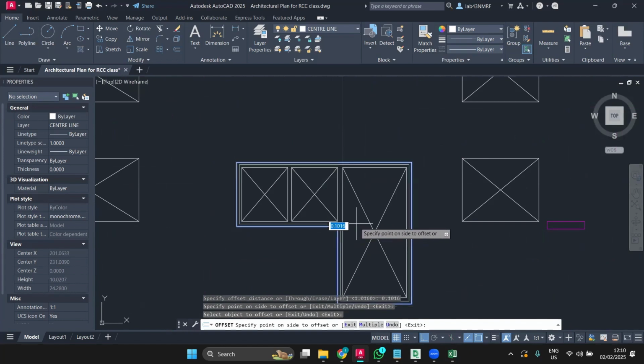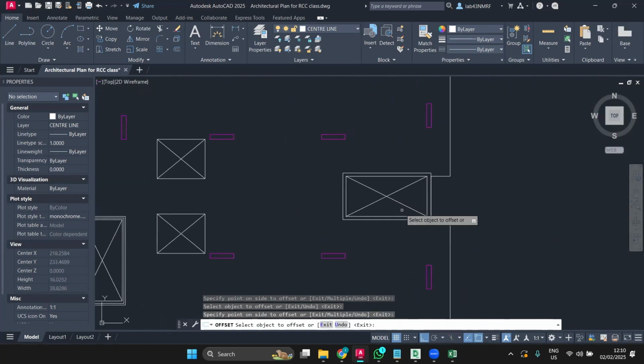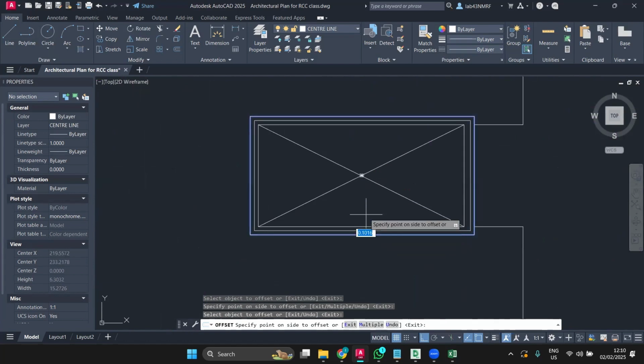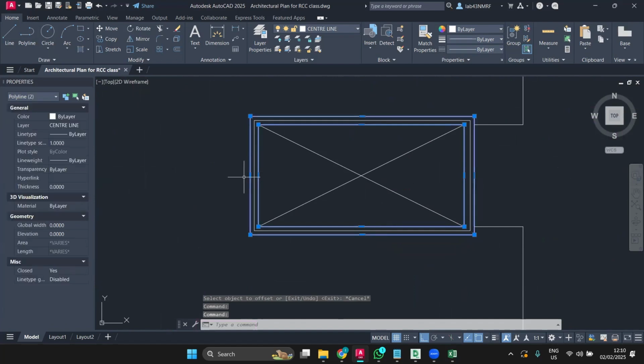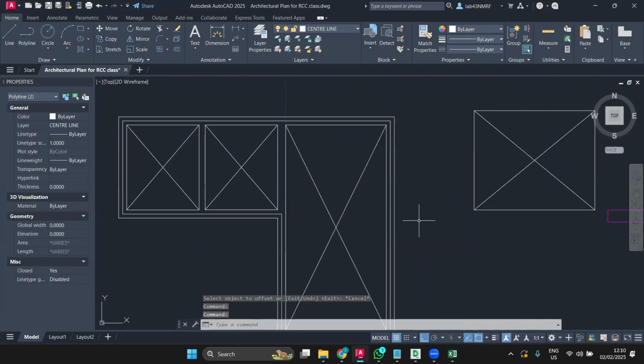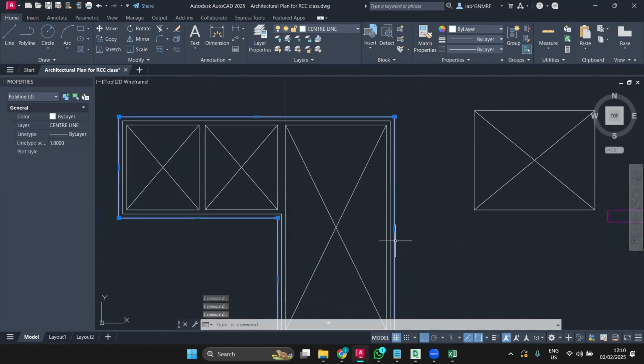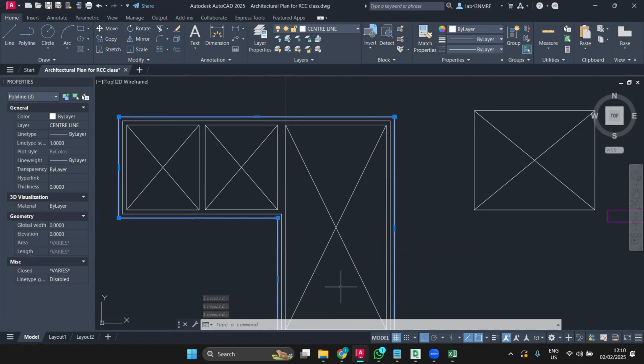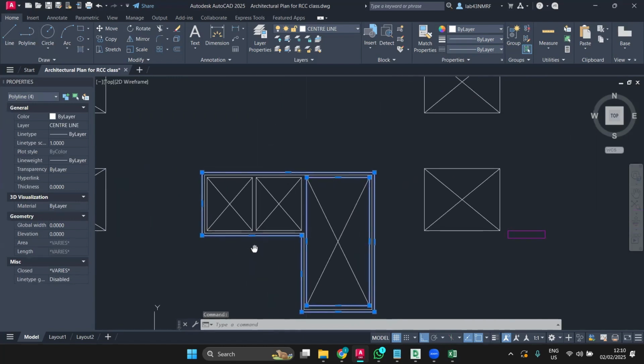So the things I told you before setting out these columns, how to place the columns and what are all the important things you need to consider while placing them, try to keep those in mind along with the concept and do it. The beauty is that you calculated the column size. We never ever assume the column size. Might be 300 by 600 is going to work, might be 300 by 800. We did not come across such kind of assumption.